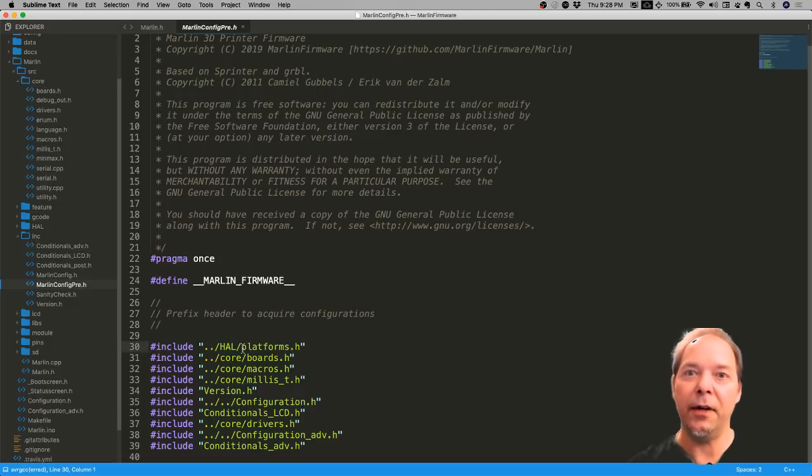And it'll actually then set certain defines and include the right HAL for the platform that's being built, and then continue from there. So it brings in all the good HAL hardware stuff. We then have boards.h, which defines the board defines. Only one of those ever ends up getting used because throughout the code it does things like, is this motherboard, and so it needs to know these boards to be able to ask that question.